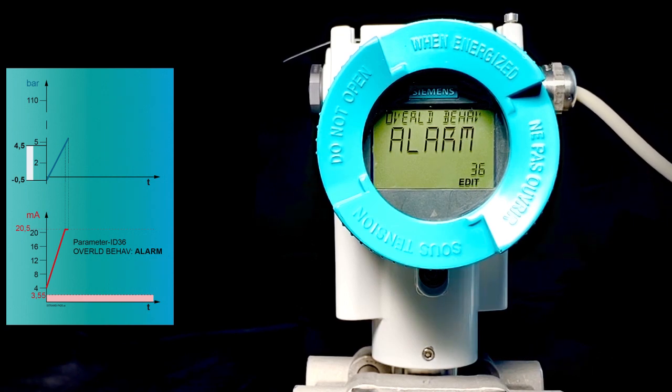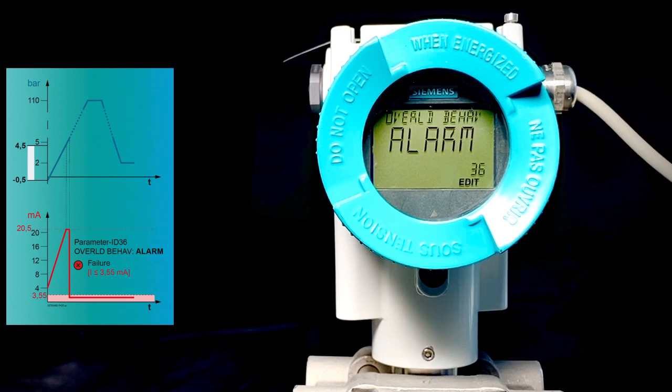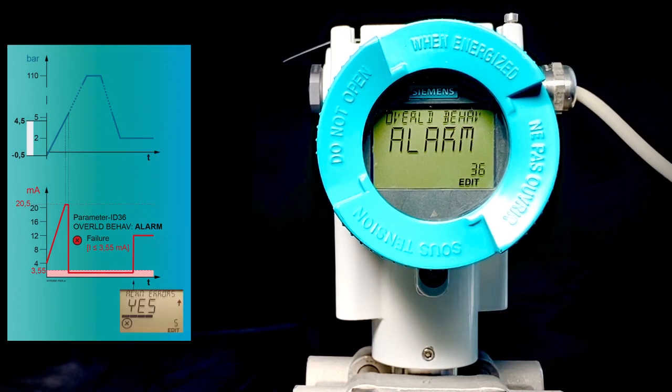This pressure value cannot be measured with the 5-bar transmitter. An additional transmitter is required for this. If the pressure transmitter is now in SIL mode in the alarm setting, the device mode's safety critical error would be activated. The current output signal corresponds to the fault current less than or equal to 3.55 mA and the diagnostic message is displayed. This safety critical error must be acknowledged.